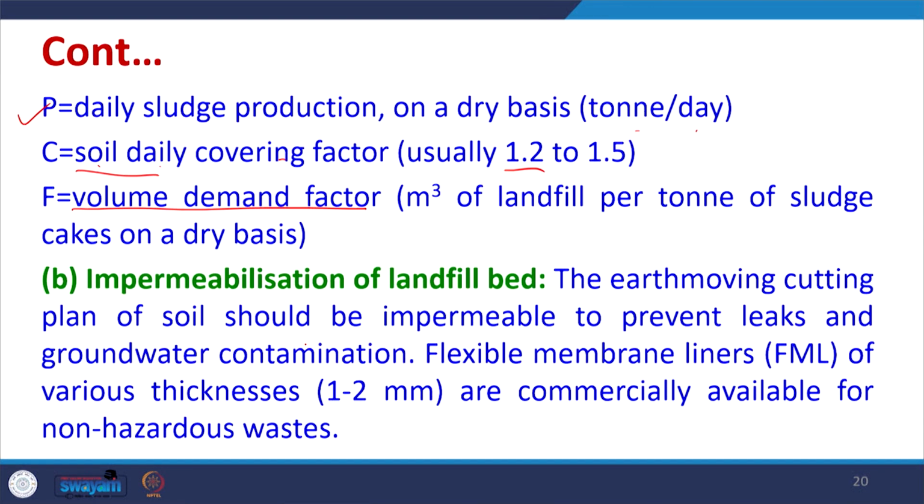Then it is very important that the landfill bed should be impermeable, that means there should be no leaching. So, the earth moving cutting plan of soil should be impermeable to prevent leaks and groundwater contamination. So, we may have to use liners. Flexible membrane liners of various thicknesses are commercially available for non-hazardous waste, and they are used so that the landfill becomes impermeable and there is no leachate generation. There is no water going into the groundwater.